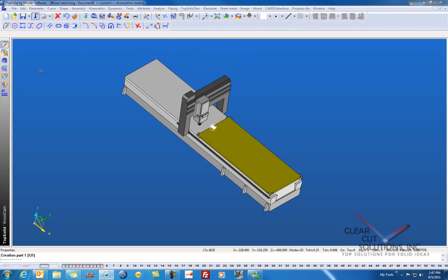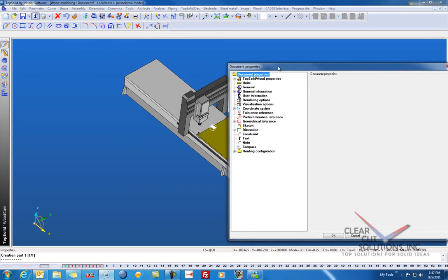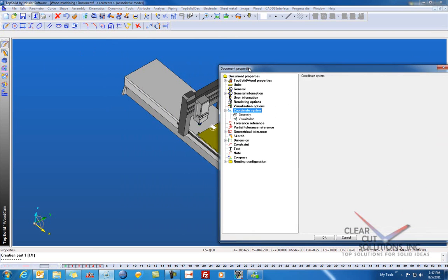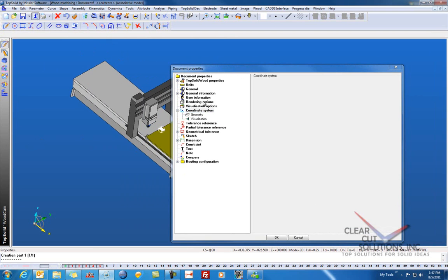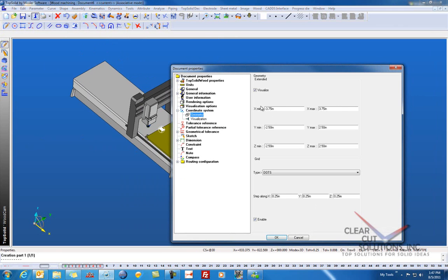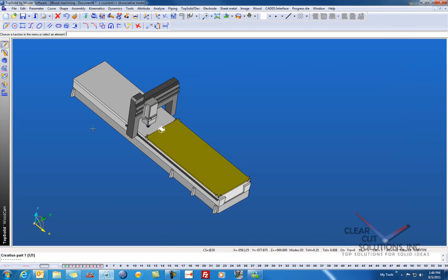And what I want to do is go in here to File Properties, and set my coordinate system, and let me just pan this over, set my default coordinate system size to be much larger. So for example, I'm going to say 100 inches there for my table length. For my Y minimum, I'll say -10 just so it's bigger, and here we'll say is 60. Why not? Okay? And what that's going to do is set the size of new coordinate systems borders.